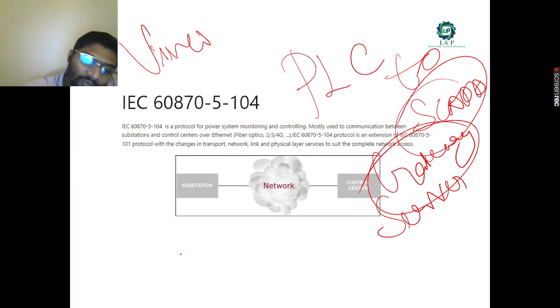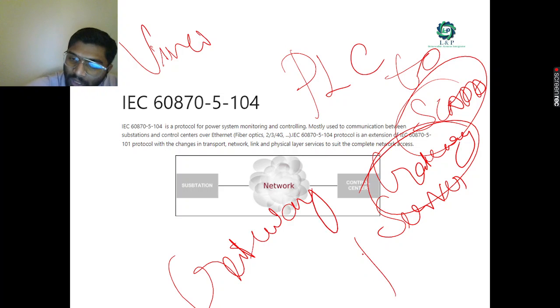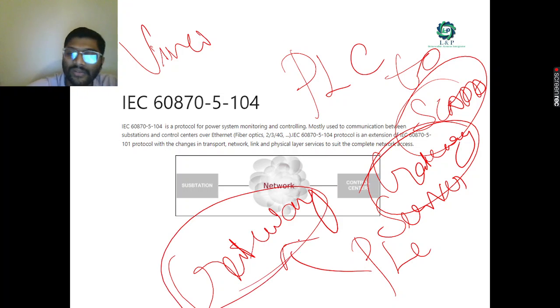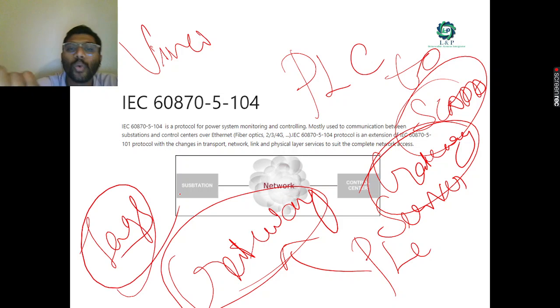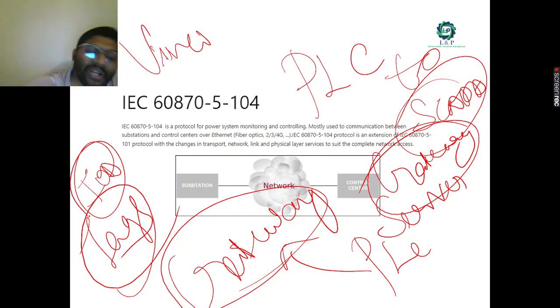You want to cross confirm whether the values you're sending from your concerned PLCs through the gateway are proper or not. You might have created so many tags, so you want to know whether the tags you created are being received, and whether the addresses, values, IDs and IOAs you created are getting passed through the gateway. You need that confirmation.